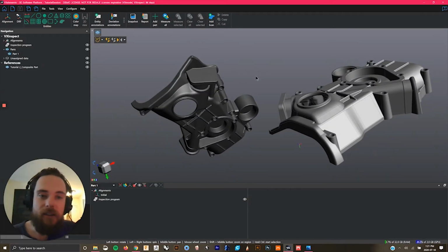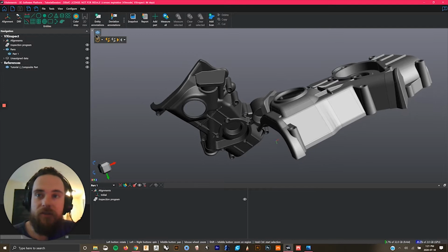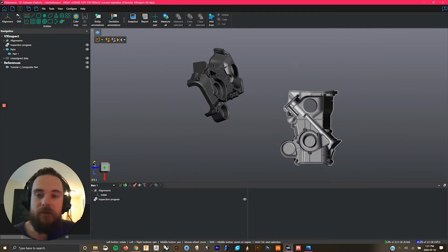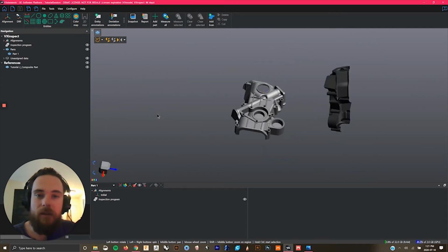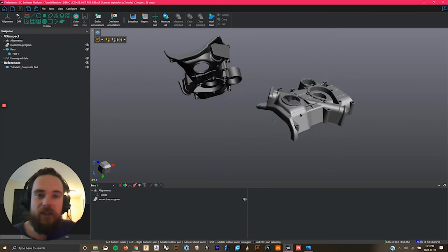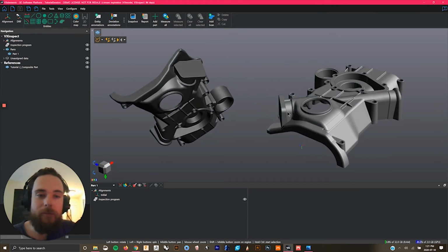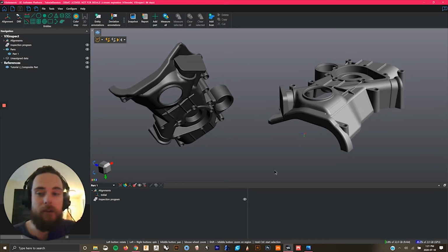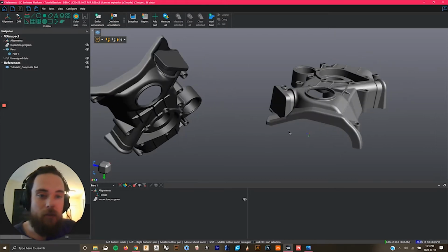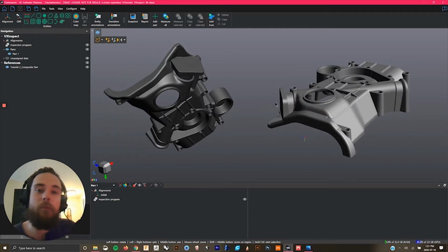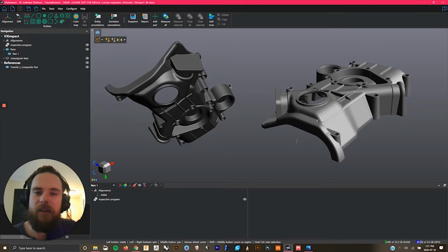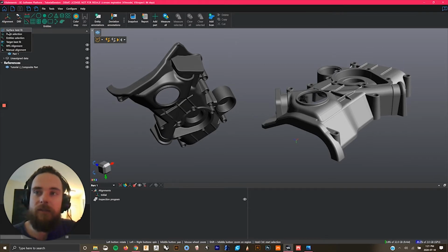When you look at the viewport here, we have some selection tools which will allow you to flip between CAD and mesh, and a viewing cube here which lets you get your ortho views. Typically when you scan a part and you bring it in, it's at its own arbitrary world space, and a CAD model that you bring in will often be aligned to its original origin, which is more than likely where we want to start our initial alignment and inspection. So let's try and do an initial alignment for this just to start off the process.